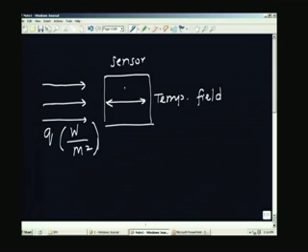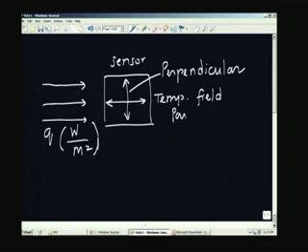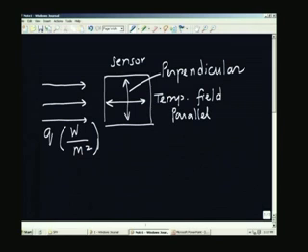That means that I could have a temperature variation in this direction. This is the perpendicular direction, this is parallel direction. So, these are basically the two different types. We may also be actually measuring heat flux in a system of coordinates other than Cartesian. So, we will come to those things a little later. I will talk about for example, heat transfer in a radial direction, radial heat flux in the radial direction and so on.